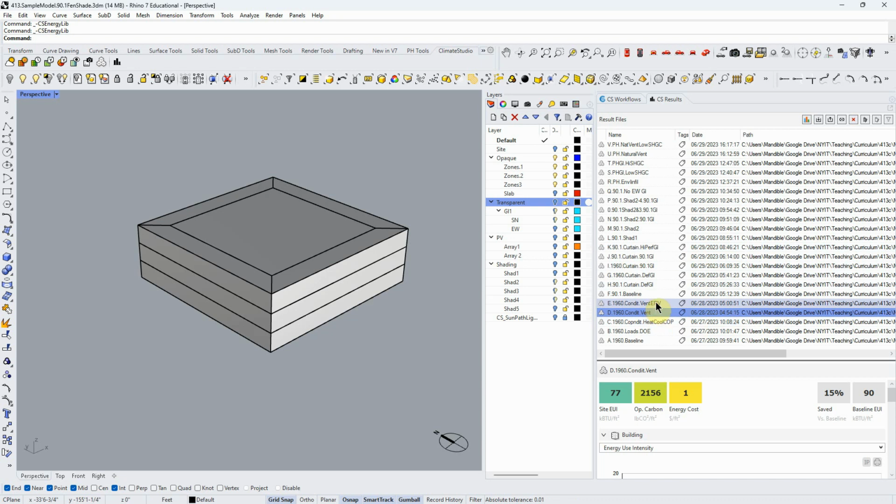When I changed to an efficient system, I'm back basically to where I was without ventilation, which is incredible. With ventilation, I added 15 kBTUs per square foot to my site EUI, and now I'm back down to 62, which means it's a wash having that ventilation system in terms of energy, and now I have the ventilation, so that's awesome.